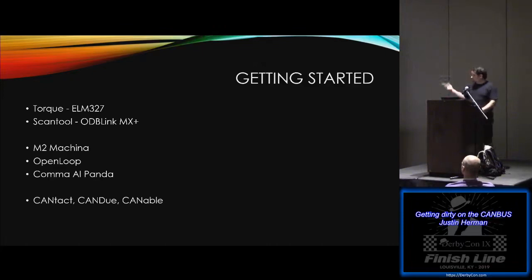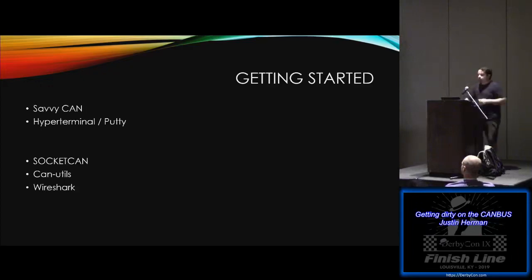I'm aware that there's CANtact, CANdo, and CANable. I don't have any experience with those. The software that you're going to use for that, at least what I used, was SavvyCAN and PuTTY or HyperTerminal. But if you're in a Linux environment, SocketCAN is a great option along with can-utils. And if you have Wireshark on a Linux machine, you can actually address CAN messages that way.